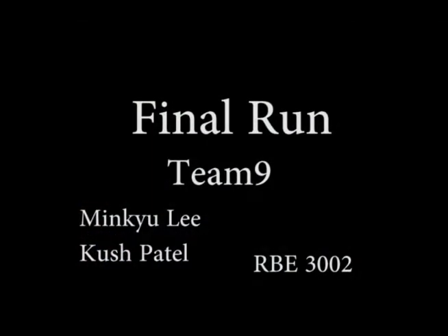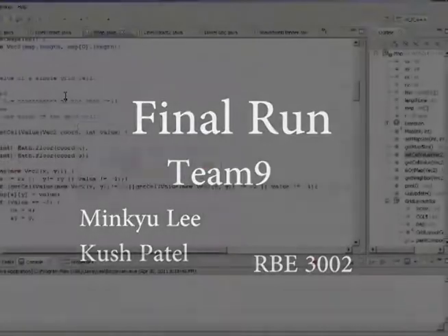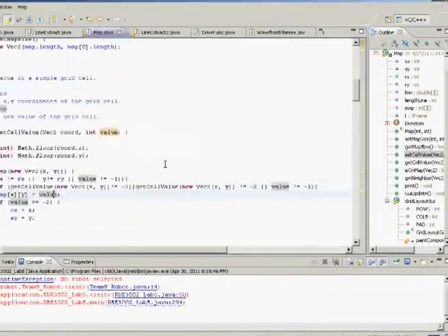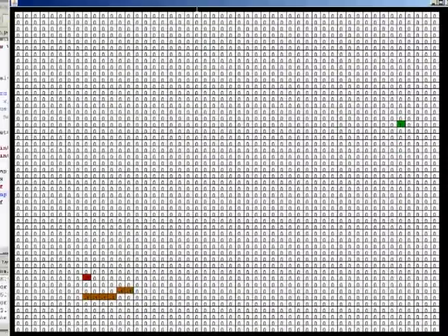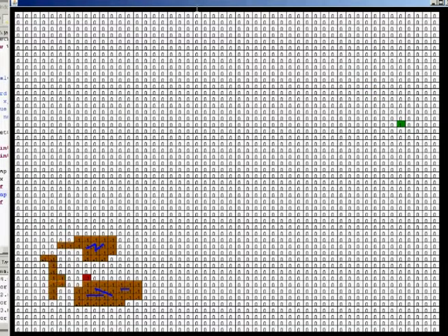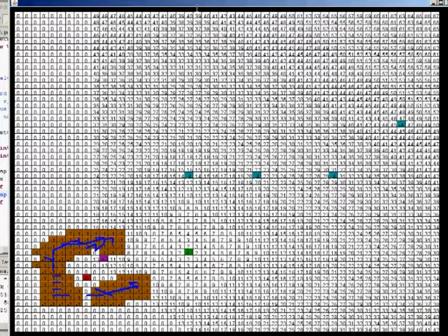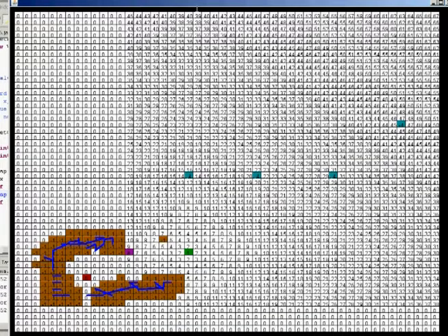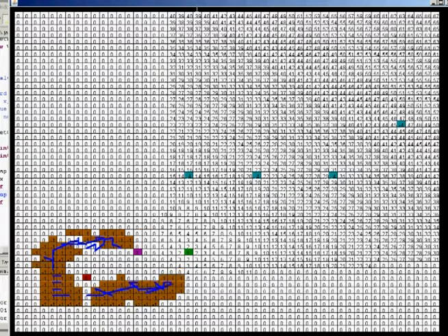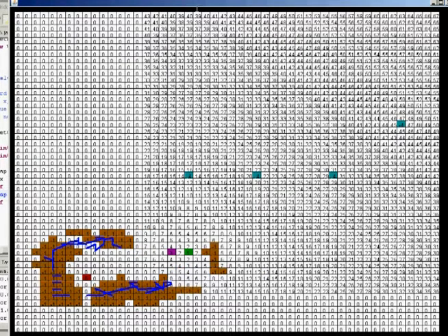We also have configuration space. Whenever the wall is occupying a grid, we also mark the four grids connecting to that grid as occupied, so we don't go through it. We consider the configuration space of getting through that blank space. So within that function, we were able to detect walls.